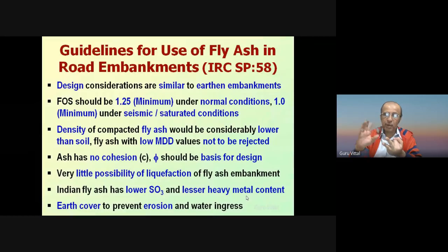The material should not be compacted. If it is compacted, the liquefaction will not occur. So we compact the fly ash to a high degree during our embankment construction, and the liquefaction chances are reduced. Third is that the material should be saturated. Whatever the silt or fine sand material is there, that should be saturated. And since we are constructing an embankment covered with an earth cover also, there is very little chance of water going inside and saturating the embankment. So the third requirement also is not fulfilled. That is why there is very little possibility of liquefaction of a fly ash embankment.